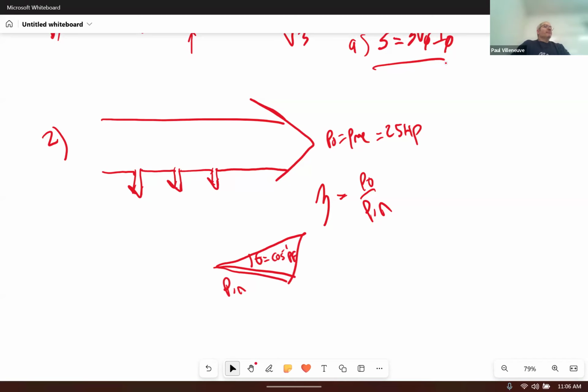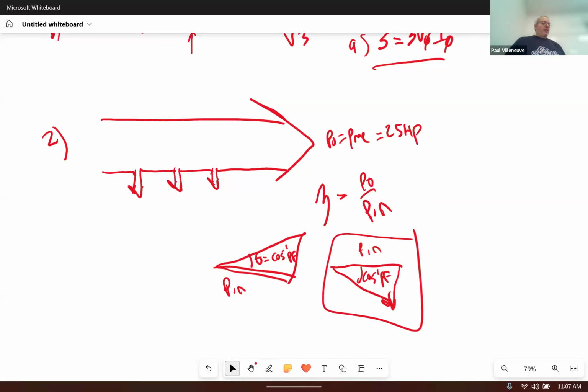Right? And I said it was a leading power factor. So in reality, the current leads the voltage. So my S actually has to go down here. Right? The angle should be negative because it's VI conjugate. So this is the one you should have done.